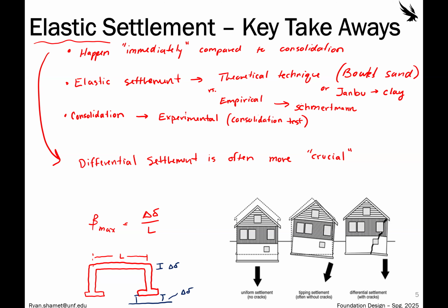So yeah, aside from that, for elastic settlement a lot of times you are going to be using Schmertmann's. There's software that will calculate that. And the most important part is finding that Young's modulus, making sure you're using the correct Young's modulus.